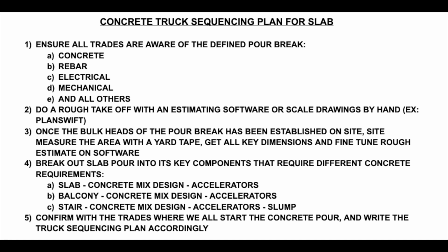Number 2, you will want to do a rough takeoff with an estimating software such as PLANSWIFT that I use. Once that estimate has been done, you can pre-book your quantity of concrete with the plant in advance. Once the bulkheads have been established by the formwork trade, then you'll be able to get some direct measurements for the lengths and widths of the pour break.